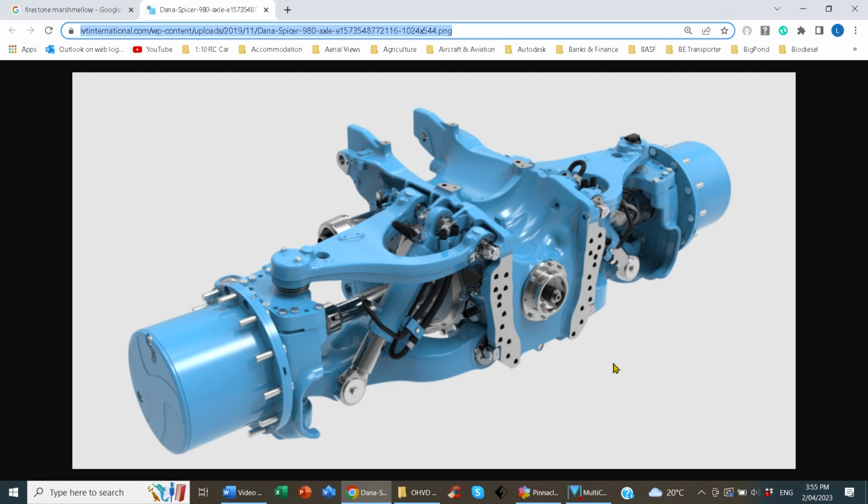Unfortunately, good independent systems tend to get compared to bad live axle systems, and it blurs the comparison. This sort of thing allows the floor of an AFV, for example, to be lower than the wheel center. The bad part of it is there's lots of joints, and a lot of those joints are vulnerable to impact, particularly if there's a steering arm run across the vehicle at the front.